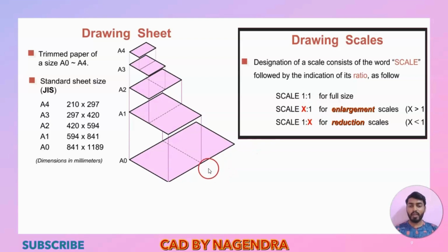So as we have discussed, this length is 100 and this width is 50. So these both dimensions we need to multiply with the multiplication factor of 2. So while creating this sketch, instead of 100, we will take here 200, and instead of taking 50, we will take double of that, 50 into 2, total 100. So here we will take 200 into 100.